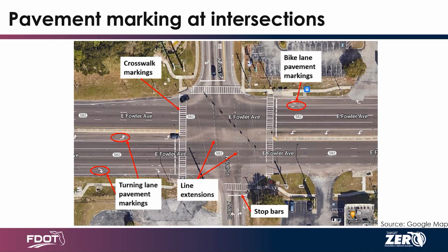So in addition to a couple of the signs mentioned, also street name signs. Those are throughout basically all intersecting roadways in the state, alerting drivers to what road they're approaching. We could have next signal ahead or intersection ahead signing, identifying the cross street. Bicycle lane signs, pedestrian crosswalk signs, and depending on whether the intersection is in a school zone, school zone signing may be appropriate.